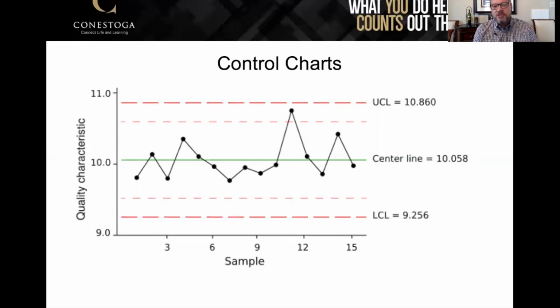It's normal to see variation around the center line. And in fact, you'll often see patterns of that variation. When the pattern changes, that's often a sign that something might have changed that may in fact cause a situation where you would actually go out of control. And out of control is when you break an upper or lower control limit. So a control chart can give you early warning before you actually have an error, just when you have a change in that pattern, right?